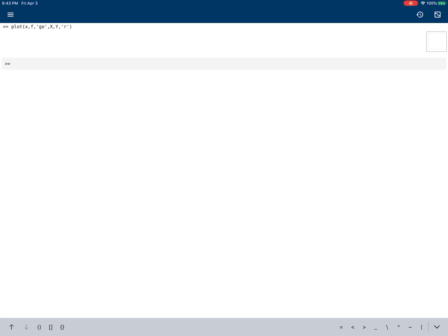So what now? We're going to try to do a Fourier transform of this function. We're going to create a discrete Fourier transform. And this is actually done very, very easily in the computer. I'm going to name this capital F. Usually the convention is to use capital letters for your Fourier transform variables and lowercase variables for your original signals. And what we're going to do here is use the function fft of the sample vector.